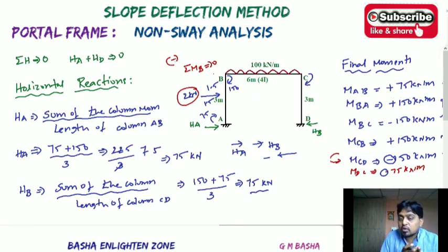This means the formula doesn't work all the time. The manual procedure is easy to remember, but if there are no loads acting, directly take the values down in this formula. If any forces are given, like point load, eccentric load, UDL, or any combination of triangular loads, then it is easy to calculate using manual procedures. But while calculating, you have to remember the logic, whether it comes under negative or positive. I will show you that also.